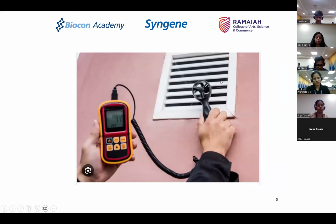This is not a return air grill, but this is an anemometer. The anemometer will be measuring the velocity across this particular grill, and then they will convert this. They will calculate the area and the percentage of blockage, and this can be measured in meters per second or feet per minute, and even in knots.